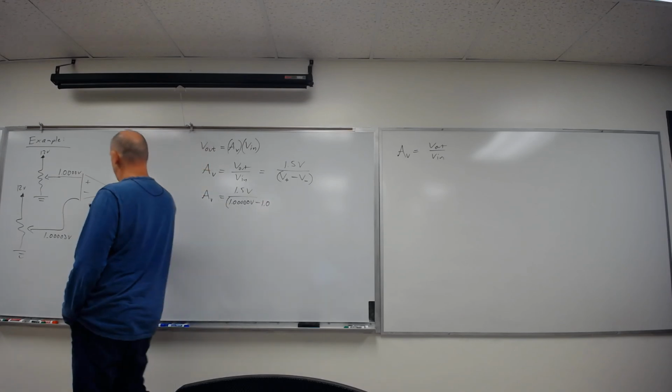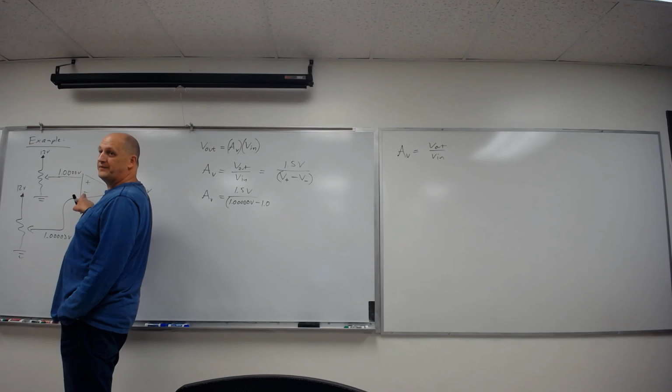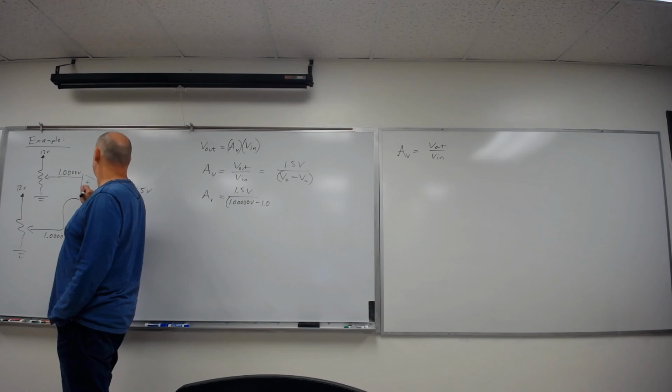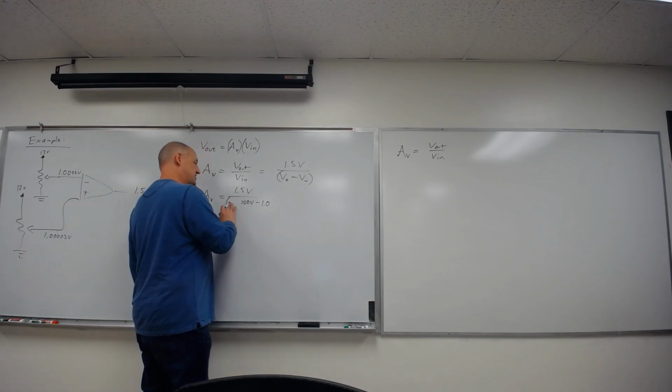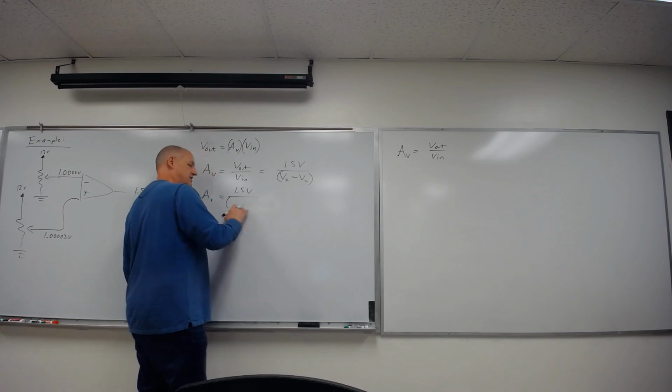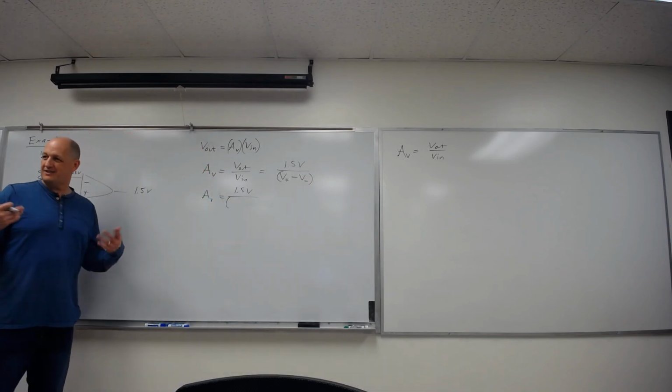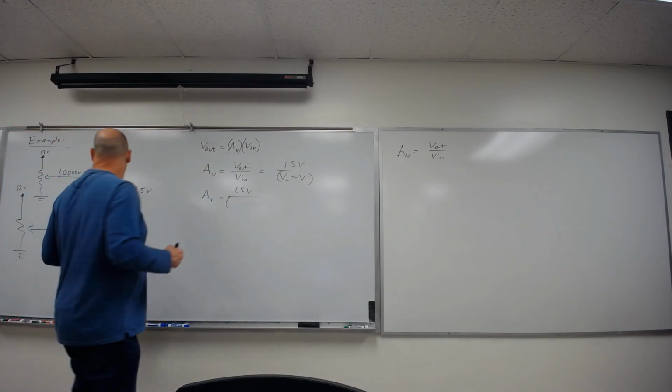I bet, is this the non-inverting input on the one you guys have on the bottom? Looks like it. Okay, I'm going to switch that real quick to match it, just because we wouldn't actually give a negative gain for the amplifier. Your circuit can have a negative gain if it's an inverting op amp. So we're going to take